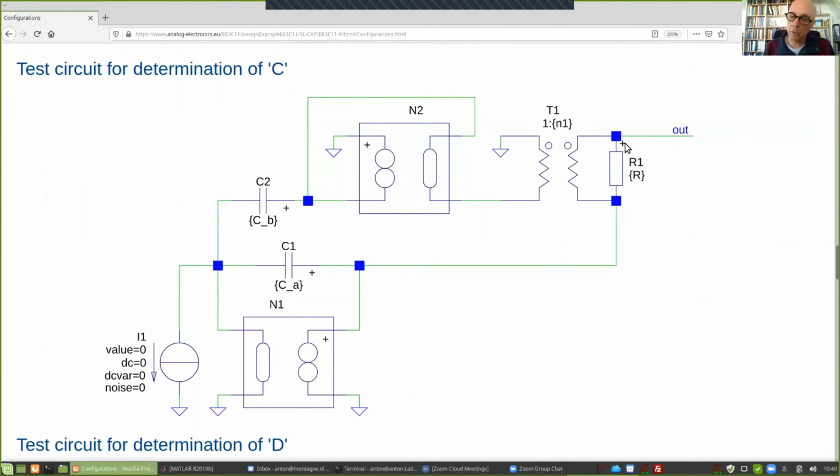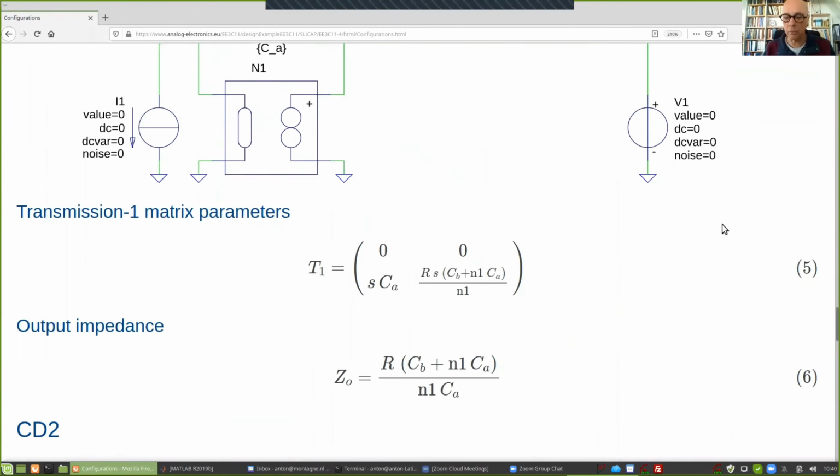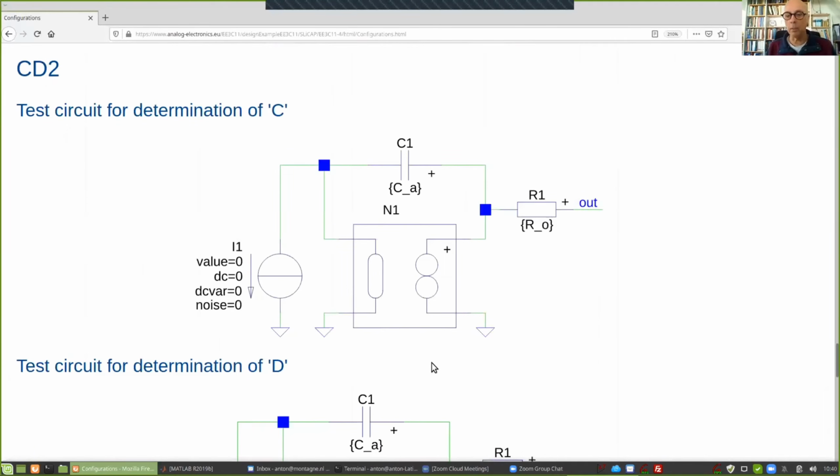We measure the current through the antenna and convert it again into a voltage. This voltage is buffered and then driven by the capacitor again and subtracted here. So if you calculate A and B and C and D from this configuration, you get this, and you find the output impedance and the transimpedance of this configuration. So this is a simple one again, in which we also sense the current of the antenna and make an integrator, and here a brute force technique for the output impedance.